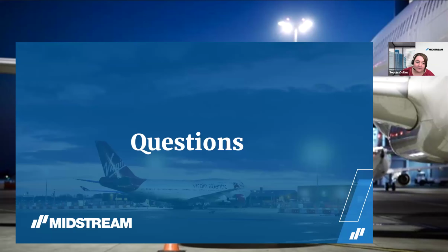How do you evaluate a multi-apron stand? I'll take on this. A multi-apron stand, so a MARS configuration, meaning we have an aircraft stand which can accommodate a large plane, or in the same surface you might accommodate 2 or more smaller planes, needs to be evaluated for all its possible combinations.